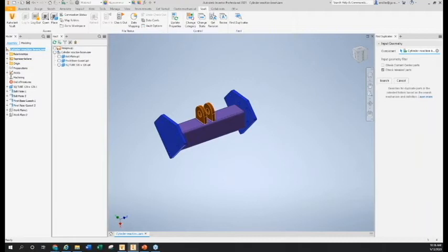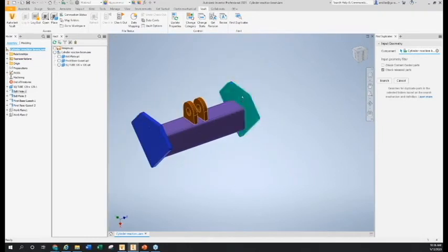On the left side, I selected the cylindrical reaction beam, which is my assembly name. Now you can see that's been added in there. Now I just go down to check content center parts. If I had bolts and nuts in here, hopefully you're using the content center. That's a great tool to not have to design those things, and you can even customize those, create a custom content center for your company if you want different properties, or maybe your hardware is a little bit different. But let's go ahead and check in there too, and then also check released parts.